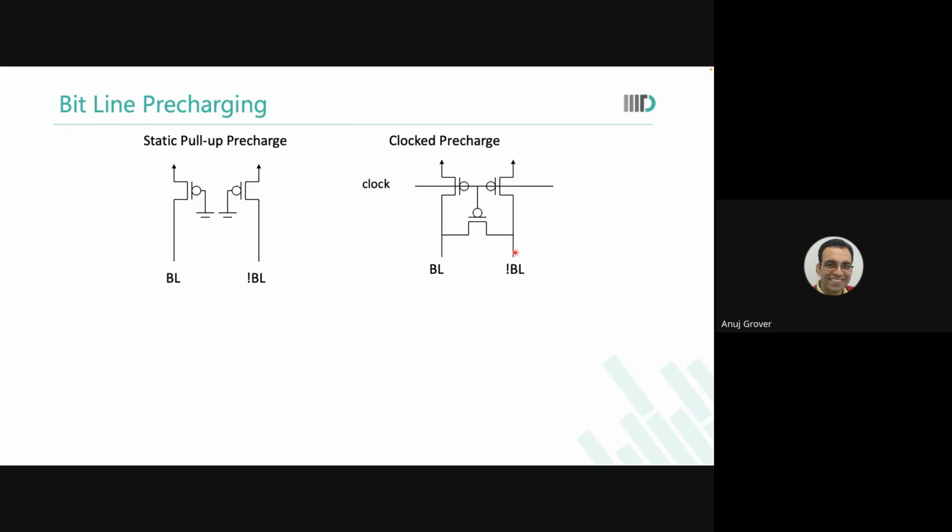You mean to say there is some leakage across them. Yeah, leakage can happen, but you know, it is deterministic, na? You have designed this, na? So it will be visible to you in every simulation that you do. It is not undeterministic. But look at it, if I did not have this precharge, you have no control over how many clock cycles I had measured or read 0 on this side and 1 on that side. You have no control over that. No visibility of that. Do you see that? So now, whatever is the disadvantage, it is in your control.